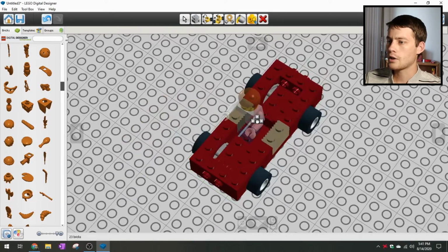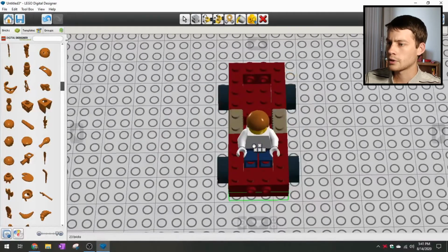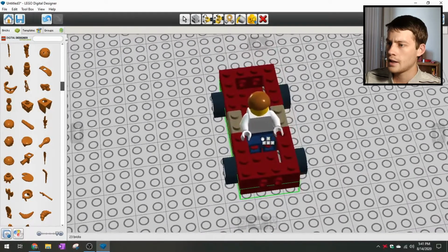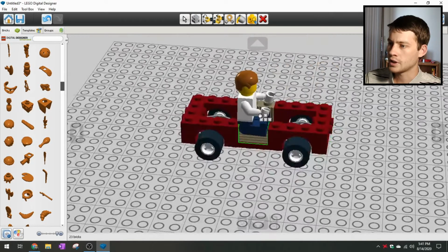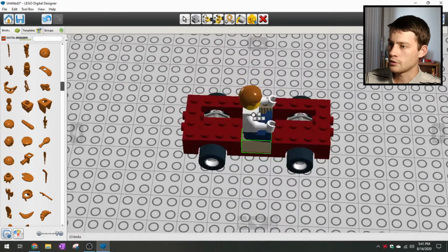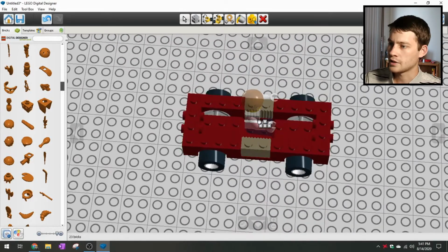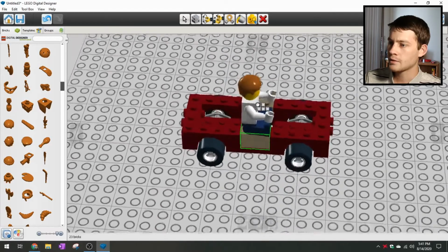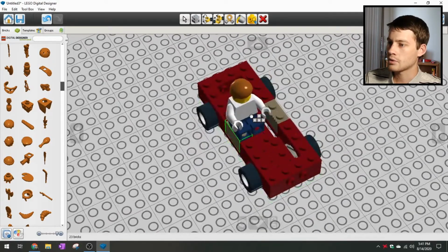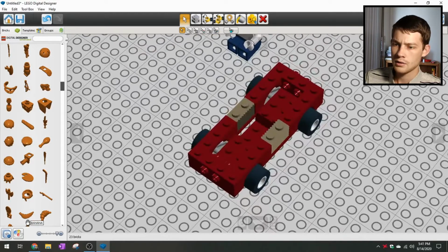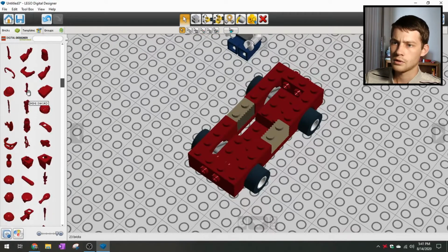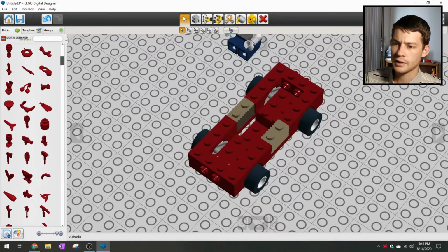Alright, so now, moment of truth, we're going to try setting it down in here. If it's up on this raised part of the chassis, it seems to do fine, but it doesn't want to sit down in the bottom part below because its arms are running into those side pieces that I just put in. So what that tells me is I need to raise up that center portion of 2x2 pieces by about 2 plates.